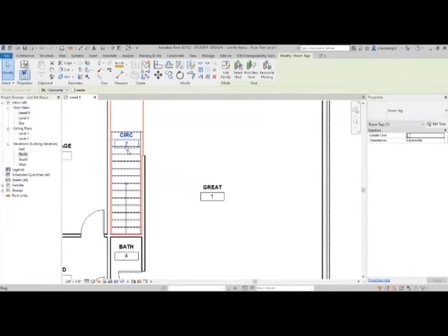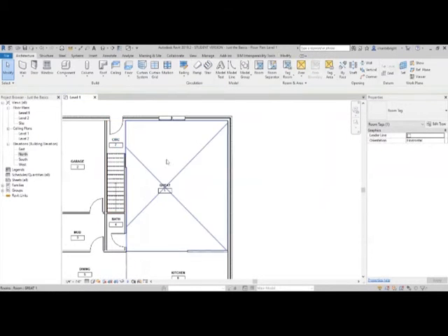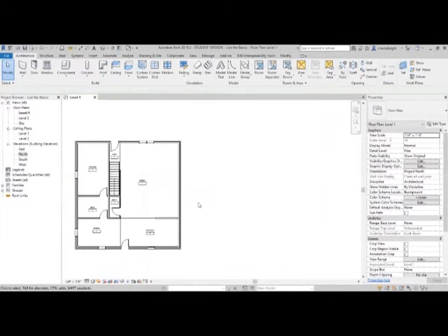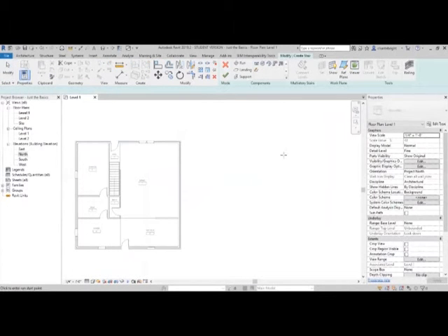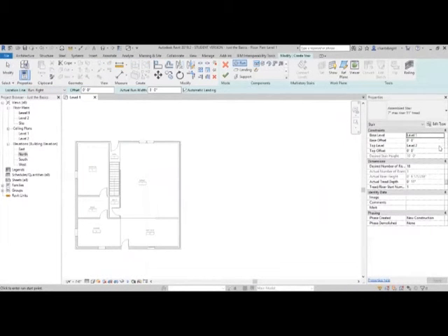Now, this changes if you want to do any other shapes. I'm just going to show you these really quick over on the side, but we can get into more decorative stair or different types of stair or different ways of building stairs in another video. I'm going to click on stair, and I'm going to keep the requirements of level 1 and level 2. I'm letting it do the math already for me, and it's going to do it based off 18.